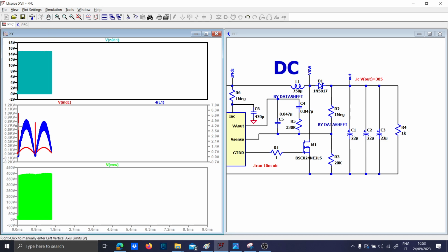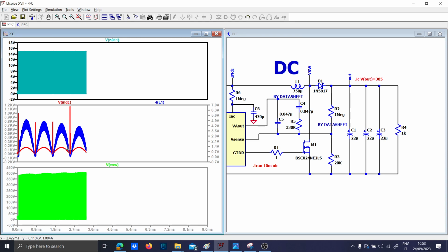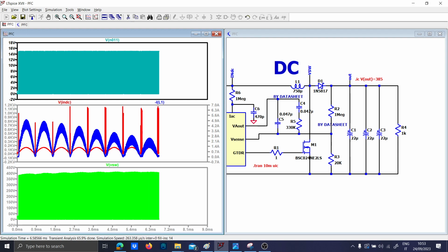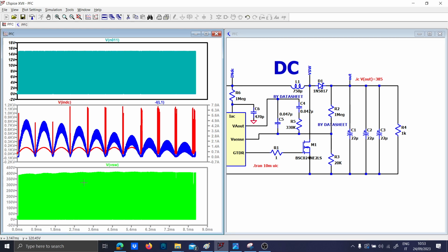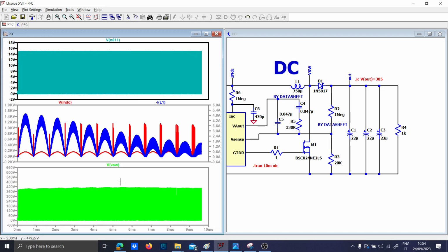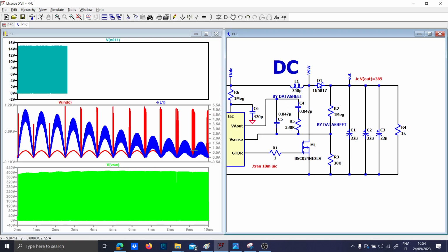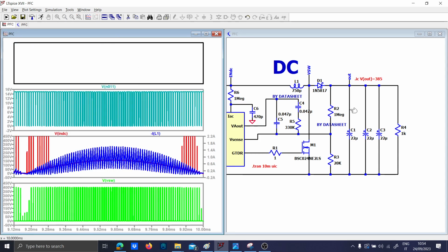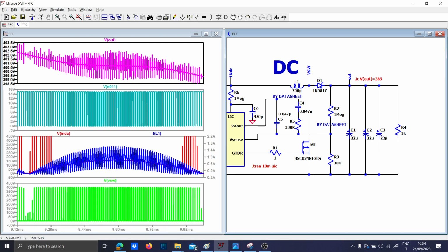You see that there is the first ripple given by the rectified current. What we can also see is the Fourier analysis. As you can see, by decreasing the load, there is still a bit of CCM here. And if we see the output voltage, it is very clean.